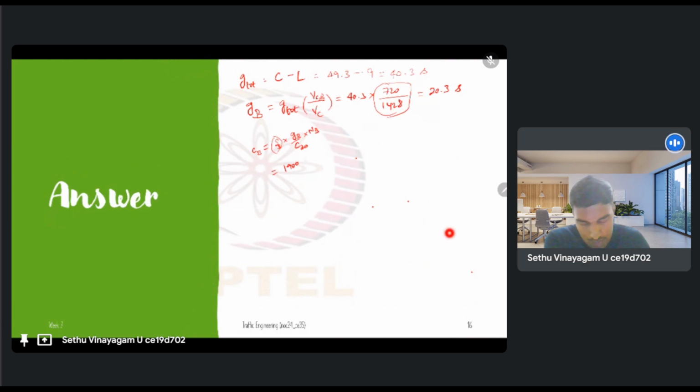So we have to multiply it by NB, and NB is 1. That is given in the question, right? So we were asked to assume that there is only one lane corresponding to the lane group for phase B, so it is 1, equal to the base flow. So into the effective green ratio, the effective green for phase B we just calculated as 20.3.